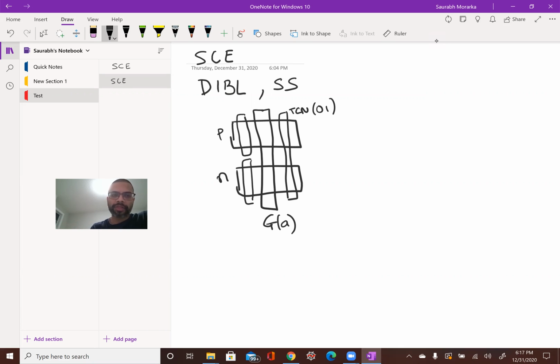Now, what Moore's law says is that to be able to shrink the circuit, you can either shrink it in the X direction or you can shrink it in the Y direction. Short channel effects are related to the X direction shrinking, which means you want to fit more and more of such circuits in the X direction. Now, how would we go about shrinking the circuit? Invariably, one of the most important things is you want to shrink this part of the device, which is the gate length.